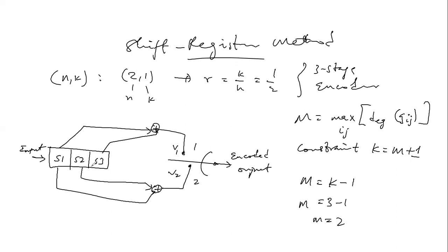That also tells the error correcting capability of this code, because the convolutional encoder is used to encode in such a way as to correct for burst errors. So the longer the stages, the more bits in error, let's put it that way, we'll be able to correct.